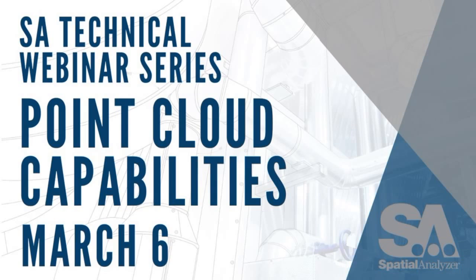But to take a quick screen capture, you just come to the reporting tab and select this little camera button. It's going to take a screen capture of this graphics view. You now have a pictures category in your tree, and then you can drag and drop that photo into your report or click on it and view it in your report bar. So from here, we've gone through voxels, looking at those deviations. Right now we're viewing our cloud as voxels, so to view it back as raw data, we go to our cloud properties, and go to our standard cloud display